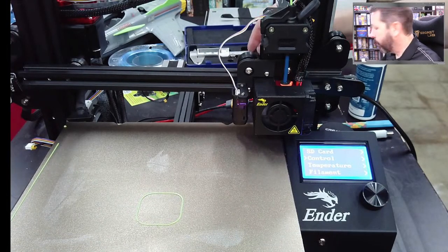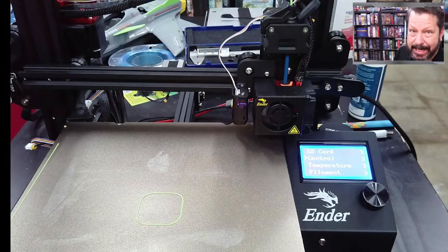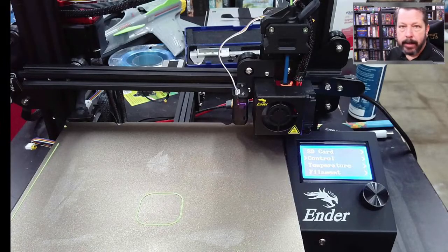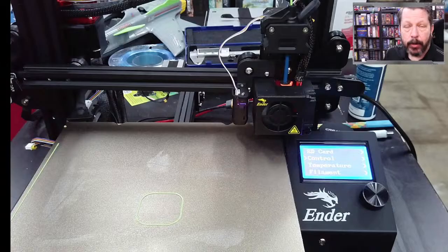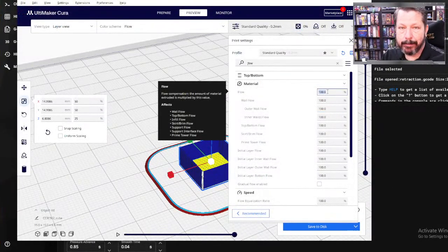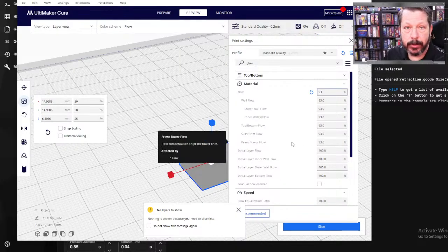and then you would try to adjust the flow based on what percentage they are. Those seem like they were probably averaging 0.47-ish or so, and I was asking for 0.4. So I would have to find a calculator, which I don't see right now, figure out how much percent I'm over extruding, go over to Cura and drop the flow rate by that percentage, so I don't know what it would be, 93%, and then reprint and do that process again. So try to hone in on getting the right amount of filament coming out of the nozzle.